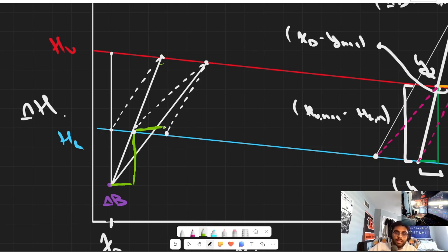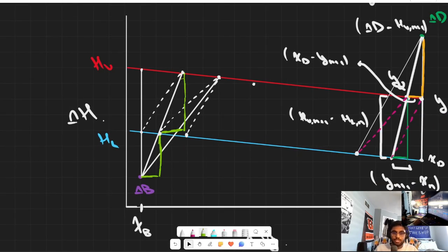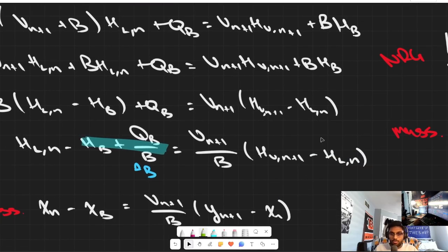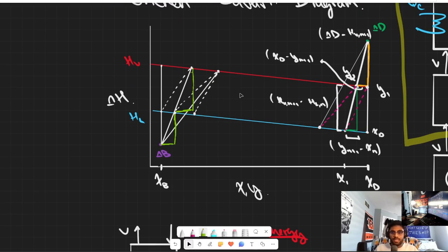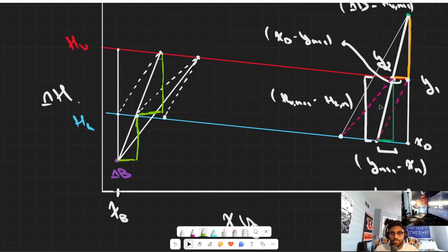And then that last bit is going to take us from that liquid composition to the vapor composition. And that is shown right here. So this is the same postulate that we used to describe these similar triangles for the rectifying section. And you can see those same similar triangles being used to justify this line here to find our vapor compositions in our stripping section.